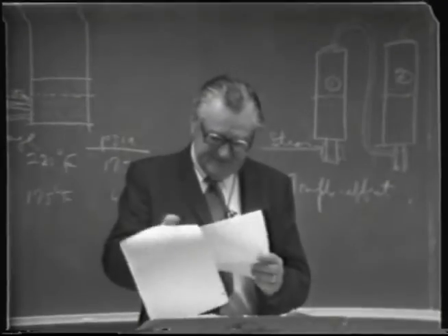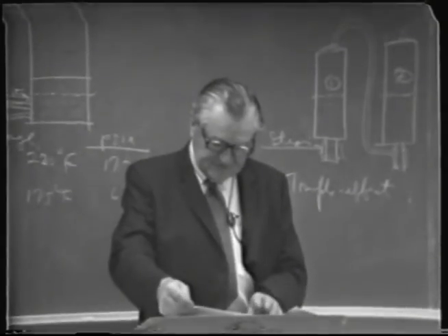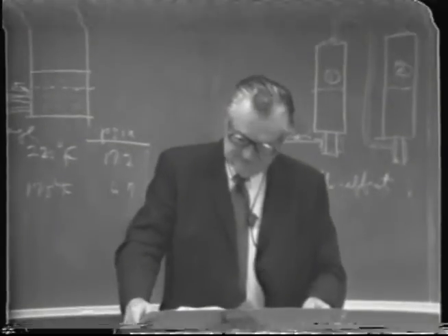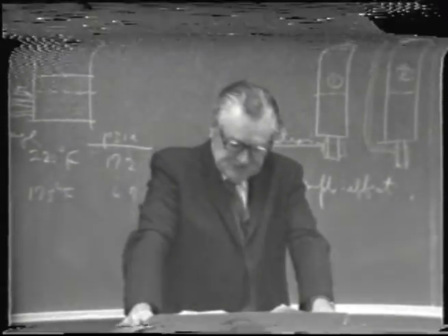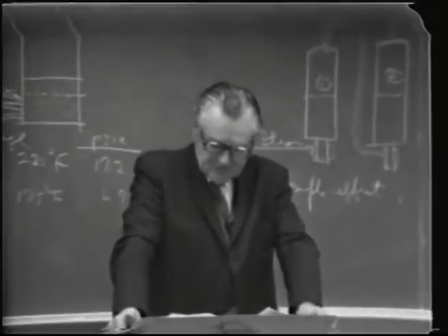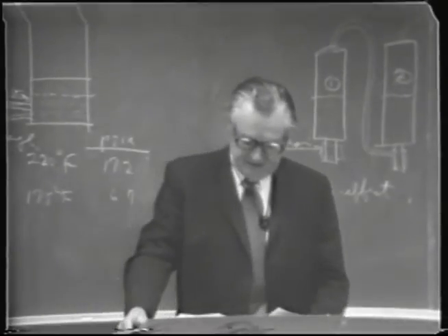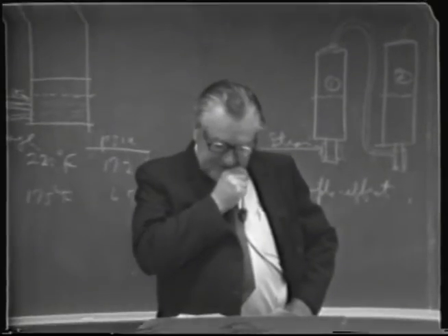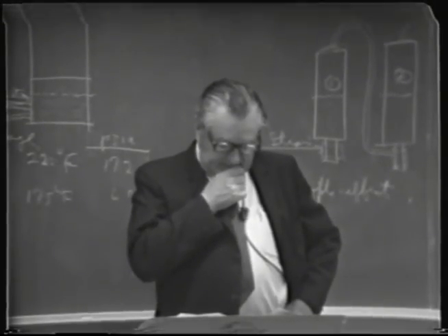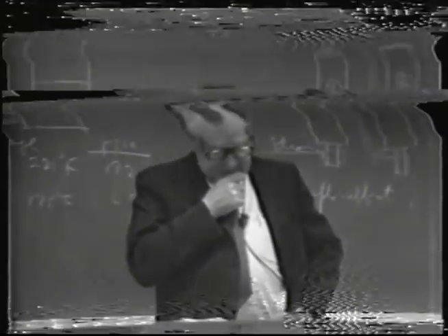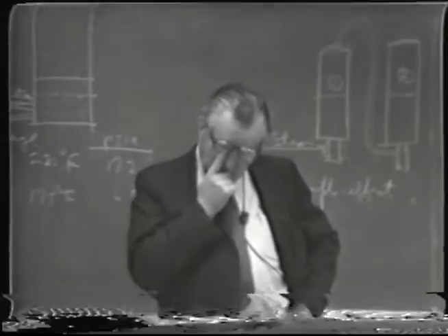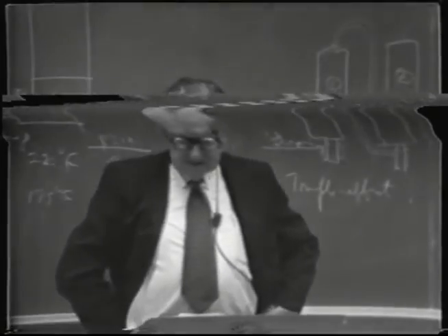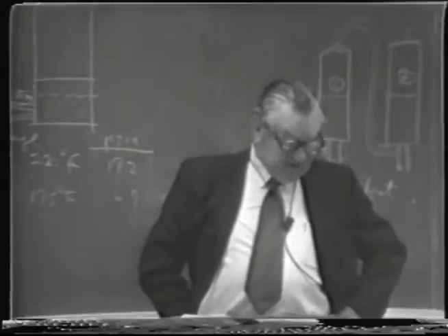And finally, G is a principle that's not used in the wine industry so much, or at all, as far as I know, but is used in other distilling industries, particularly rum, and in essence the whiskey or grain spirits, where the material to be distilled is run into a beer column or stripping column, and may have 2 or 3 or 4 concentrating plates at the top, or may not have any.